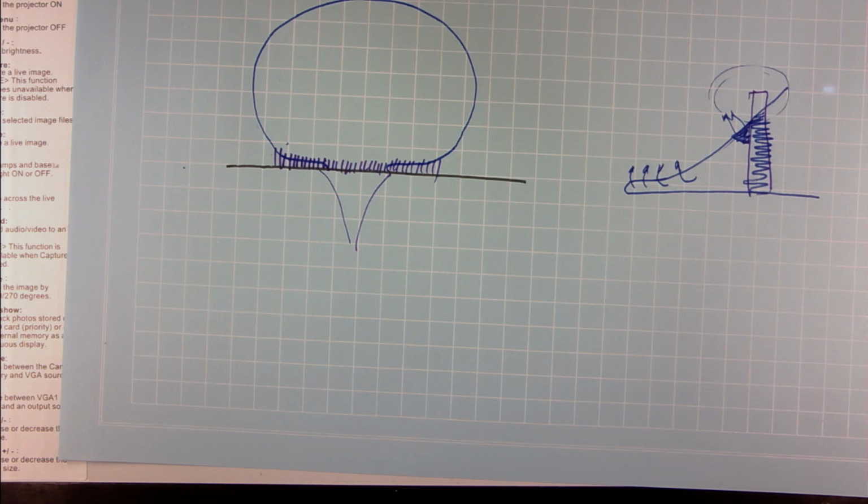Now, what is the fundamental limit for critical heat flux? The rate at which I can take vapor bubbles away from the surface, right. But the other limit is how fast can I replenish that liquid that has become vapor, how soon can I fill it up with liquid.